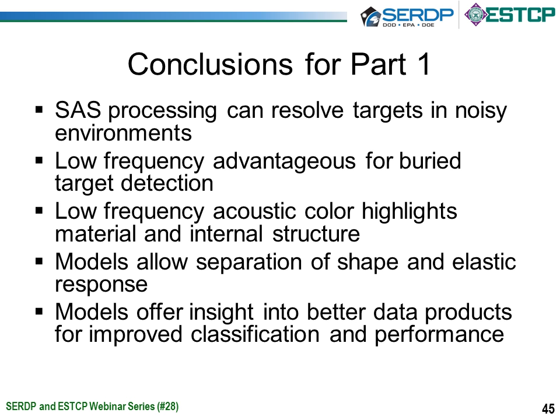But in conclusion, the synthetic aperture sonar data products are highly information rich. This is because you're looking at the backscattering response over a very wide variety of angles. And furthermore, when we look at low frequencies, we can excite structural modes. This modal excitation has a lot of information which has discriminatory power. And additionally, on the numerical modeling side, we gain insight because we're looking closely at the physical scattering mechanisms that help us determine what may be useful features during the classification process. And that wraps it up for my talk, and I'd be happy to field any questions.